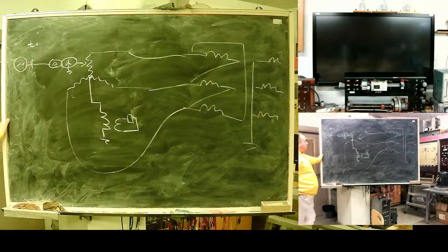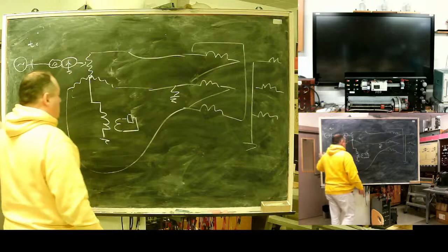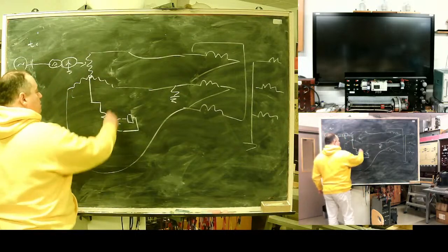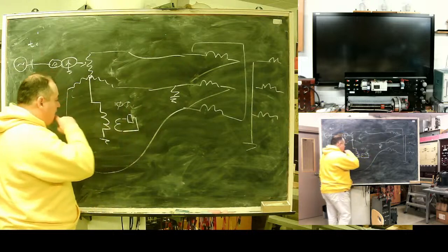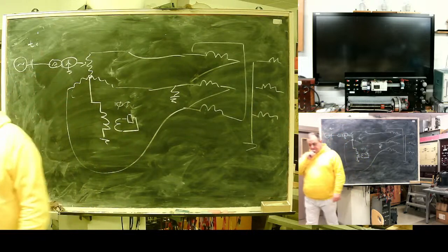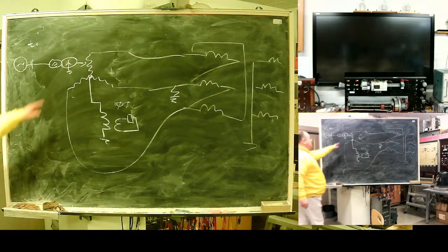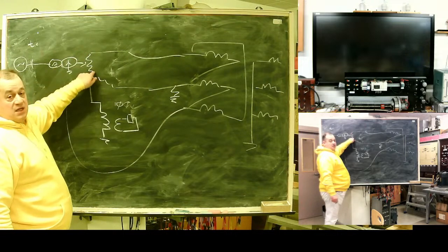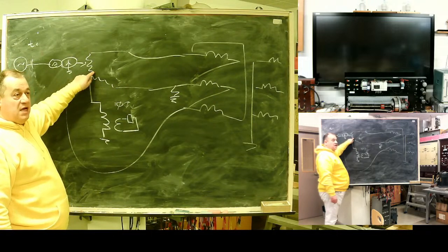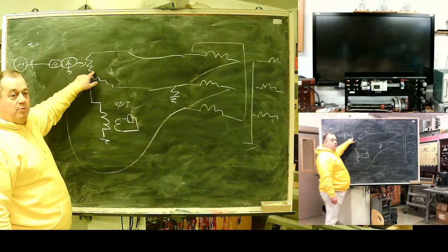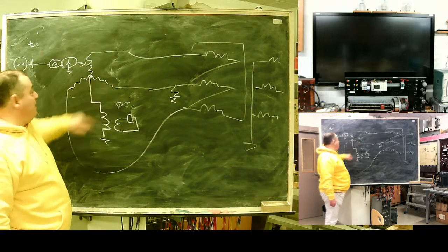In case of earth fault, here will be what? 100 volts. But earth fault can occur here, but it also can occur here at the neutral. It is not a giant problem until a second earth fault occurs somewhere.